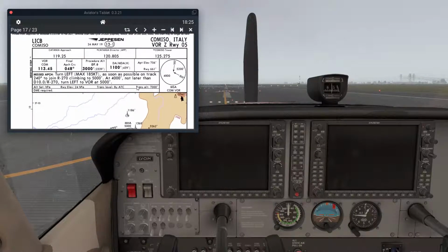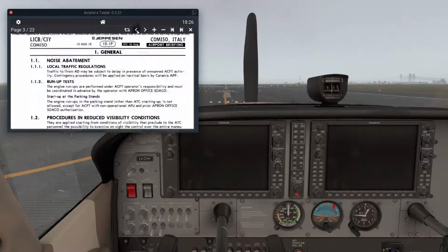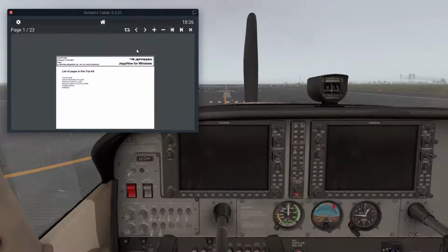Now we have power from the GPU. What we're also going to do is select, I'm sorry, I said GPU, but we're going to go ahead and select APU for the essential power. And I'm going to go ahead and move my synchronize switch down here. But this has pretty much all been dumbed down for us. Back in the day, you used to have to synchronize the frequencies before switching line contact and stuff. Just crazy stuff. But that works for APU. And then we'll also turn on the galley power while we're sitting at the gate.